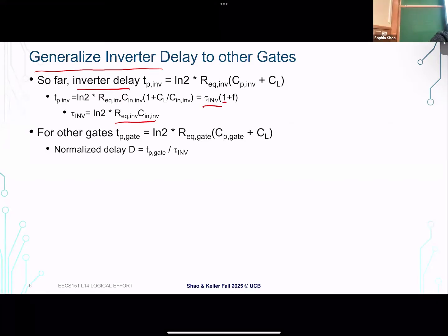And we can partition this, again, we mentioned this is like the parasitic delay, right? The intrinsic delay that we need to charge and discharge a parasitic capacitor as part of the gate. And this is a fan out delay, right? This is related to how big of a load I'm driving compared to my own strength, right?